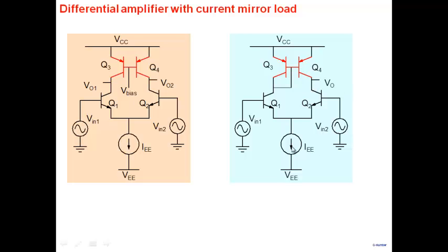Say this is 2 milliamperes. Okay? If this is 2 milliamperes, you'll get 1 milliampere here and 1 milliampere here. Let's say it divides. This 1 milliampere will flow through Q3. What will it do as it flows through Q3? This is a current mirror. So exactly 1 milliampere flows here, and this also requires 1 milliampere here. So there is no problem.